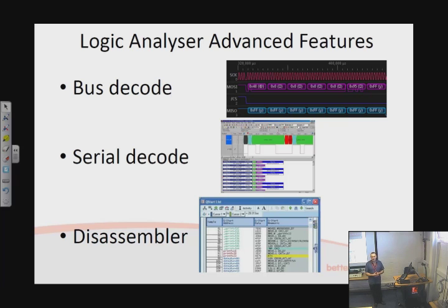So you can imagine that requires quite a sophisticated understanding built into the logic analyzer of the microprocessor's instruction set. But the prize that we get for that is an actual display of the very instructions. We can see what the microprocessor itself is thinking. It's a thing called a disassembler. So in other words, it's tracking the very instructions being loaded into the device's memory.